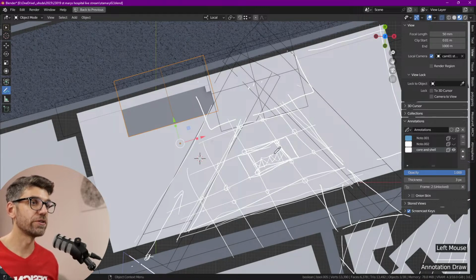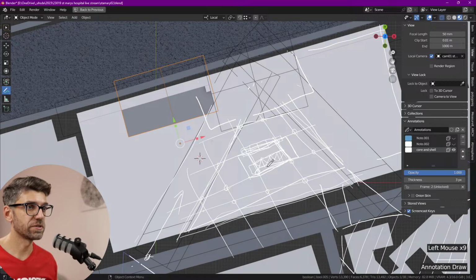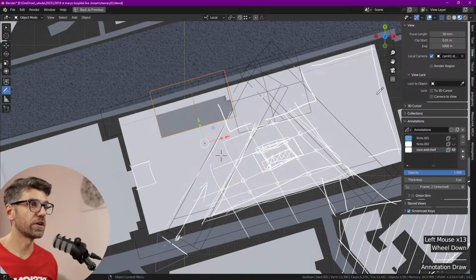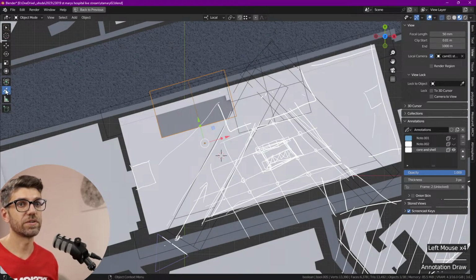So we're going to have lots and lots of lifts, probably 8 lifts, 4 in one direction and 4 in the other. Might even need more. Like hospitals need so many lifts. And we'll still have cores in here for emergency access. They can be somewhere along the edges, as long as our distances work. But just looking at them, the distances should work okay. Maybe that one there is what? Let's measure.